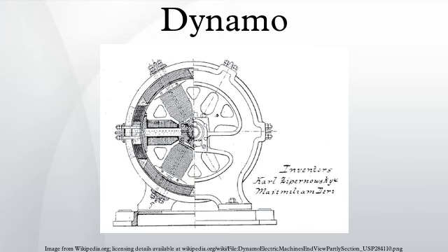This design was inefficient, due to self-canceling counterflows of current in regions that were not under the influence of the magnetic field. While current was induced directly underneath the magnet, the current would circulate backwards in regions that were outside the influence of the magnetic field. This counterflow limited the power output to the pickup wires, and induced waste heating of the copper disc. Later homopolar generators would solve this problem by using an array of magnets arranged around the disc perimeter to maintain a steady field effect in one current flow direction.